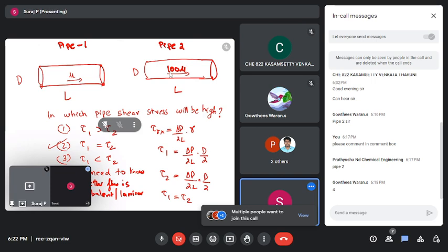Important parameters to study the flow are velocity of propeller tip, which is given as pi into n into d, where d is the diameter, and g is the acceleration due to gravity. The lab scale model is 1 by 100 of the size of the actual propeller. The rotational speed of the lab scale model to the nearest integer should be dash rps.